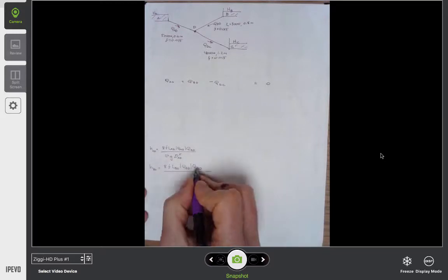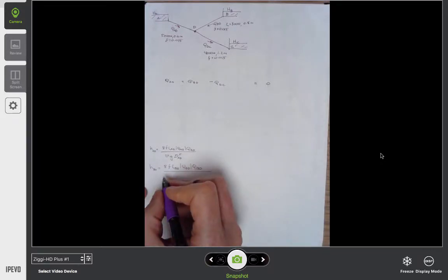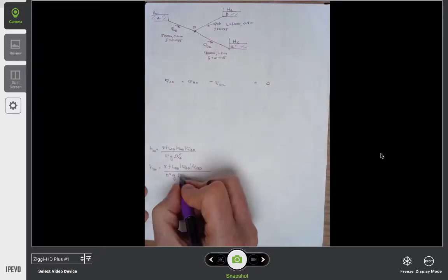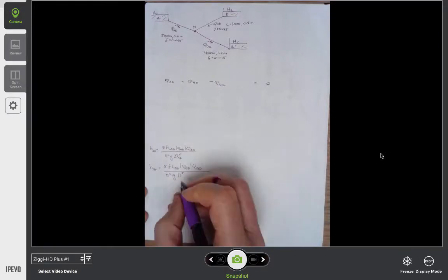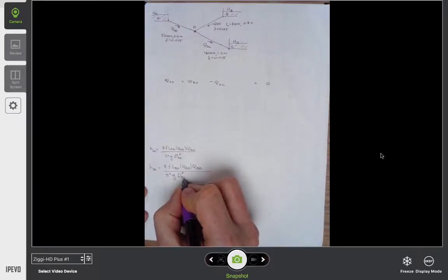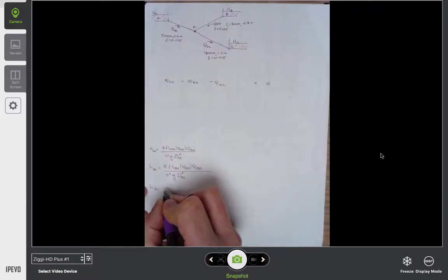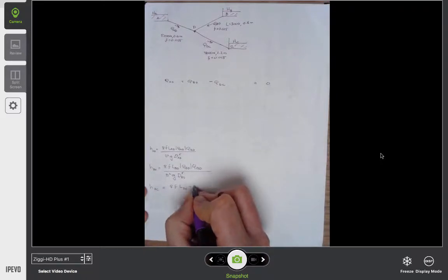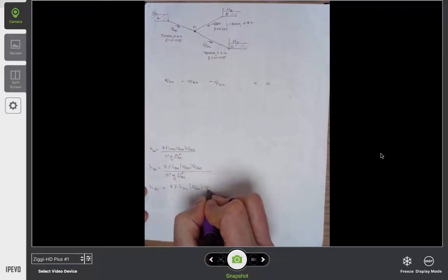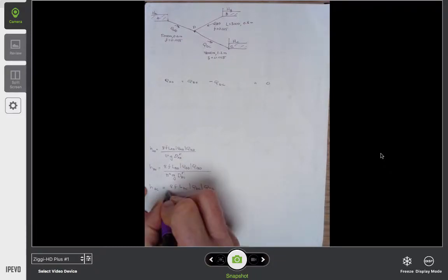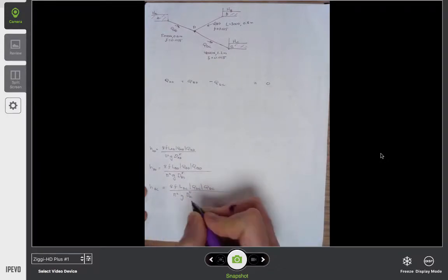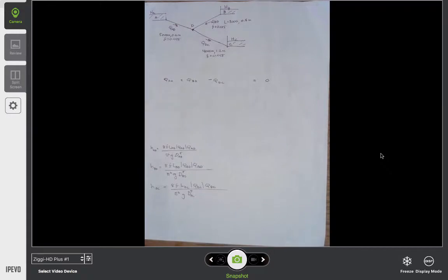I'm using that so that this computed sign of Q keeps track of flow direction. If we get a negative result, that means that the assumed direction and the required direction are opposite, but otherwise the numerical value is correct. Head loss in DC is 8 f L_DC Q_DC |Q_DC| over pi squared g D_DC to the 5th power. Those are my head loss terms for the pipe losses.